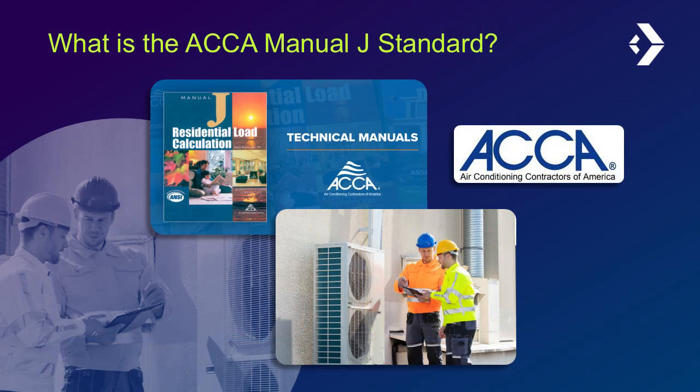When we talk about doing a load right, we're really talking about Air Conditioning Contractors of America, or ACCA Manual J. And ACCA Manual J is the national standard. It's the playbook for calculating residential heating and cooling loads. Manual J provides us with the recipe for calculating loads. It ensures we're sizing equipment based on real data, not guesswork. The recipe, as we refer to it here, includes formulas, methods, inputs, and correction factors.